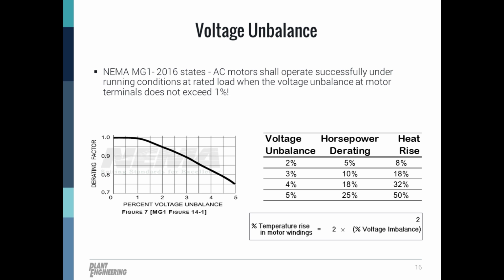So always keep in mind that voltage unbalance directly leads to current unbalance. Industry rule of thumb is that for every 1% voltage unbalance, a motor can see 7 to 8% of current unbalance. So a high current unbalance is detrimental to the motor operating conditions. Again, higher currents on individual phases can lead to hot spots in the motor windings, and thus early failure.